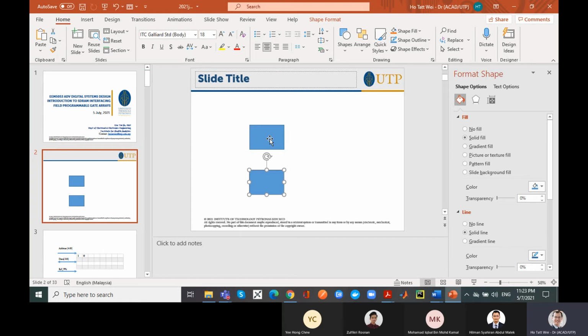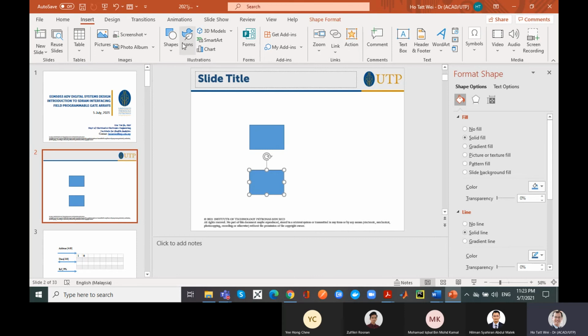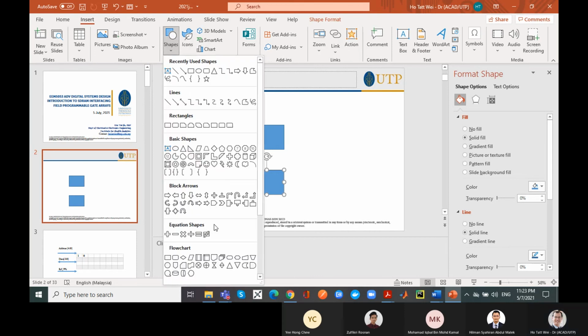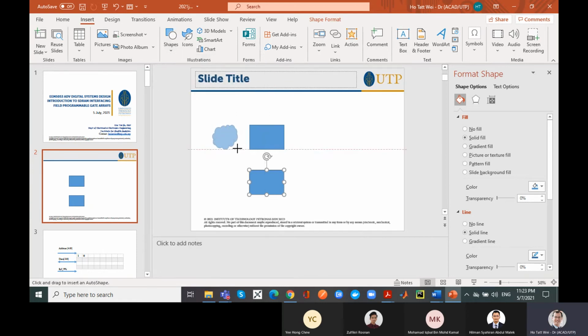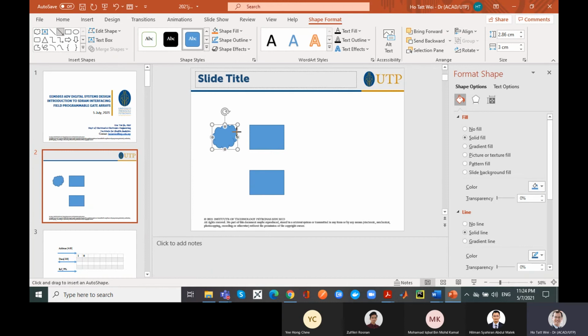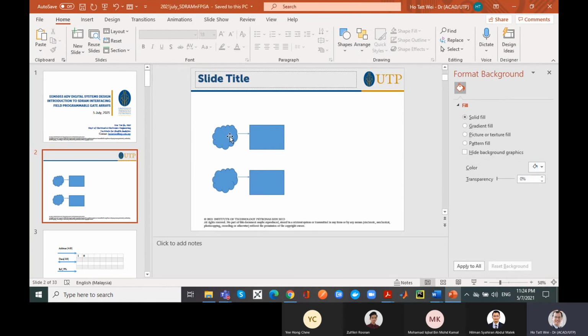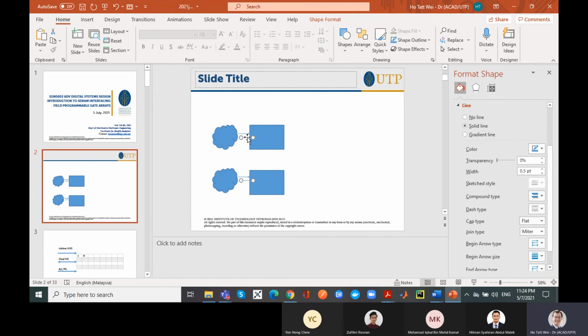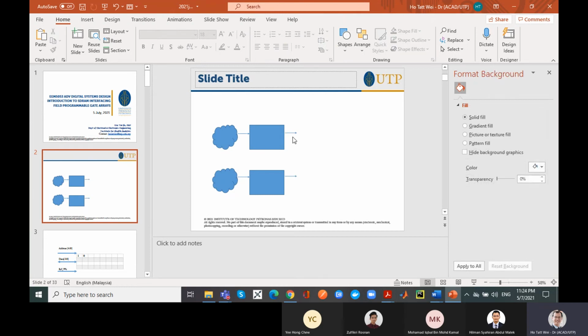Okay, your state transition diagram is basically nothing else but saying, I have a bunch of combinational logic. Okay, here's my cloud of logic. This combinational logic is driving the input of the flip-flop. And I think you know, right? Every kind of state machine always has this form, right? Combinational logic driving the input of the flip-flop, right? Correct? Yes. So you always say that the output of the flip-flop is the state, right? And then you have the state assignment problem and all that kind of stuff from digital electronics, right? The output of your flip-flop is your state, right?